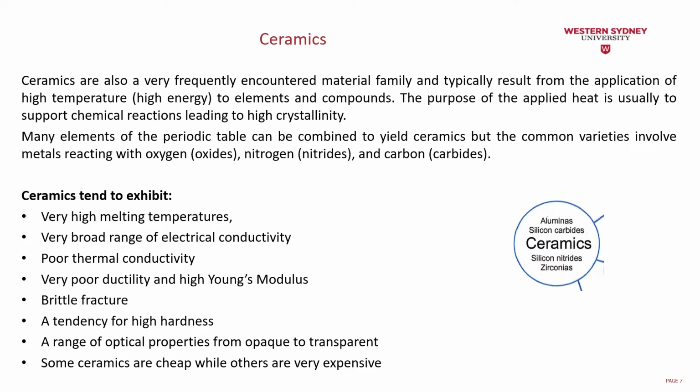The ceramic properties are very high melting temperatures, a very broad range of electrical conductivity, poor thermal conductivity, very poor ductility and high Young's modulus, and brittle fracture, of course, with a tendency for high hardness, a range of optical properties from opaque to transparent, and also some ceramics are cheap while others are very expensive.